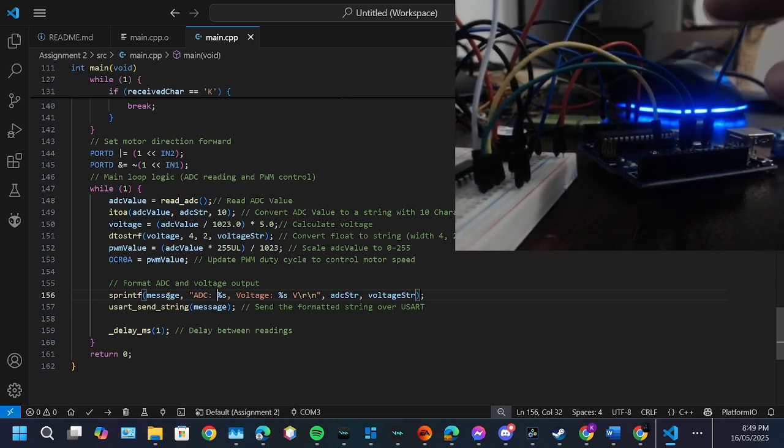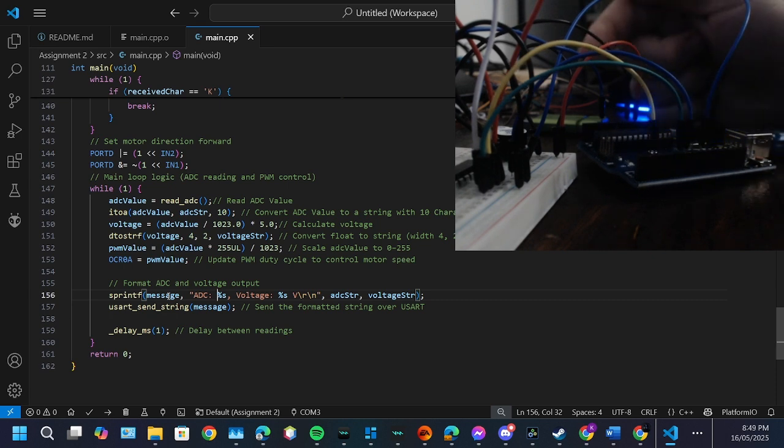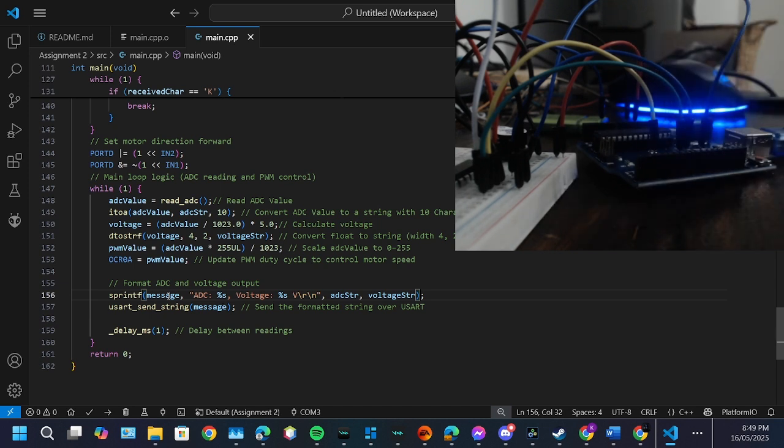Then this pin here connects to the buzzer, which is digital pin 9. Then analog pin 2 connects to the middle pin of the potentiometer. Then these pins here, the black one is connected to ground and the ground rail. Red one is connected to the 5 volt rail on the breadboard.